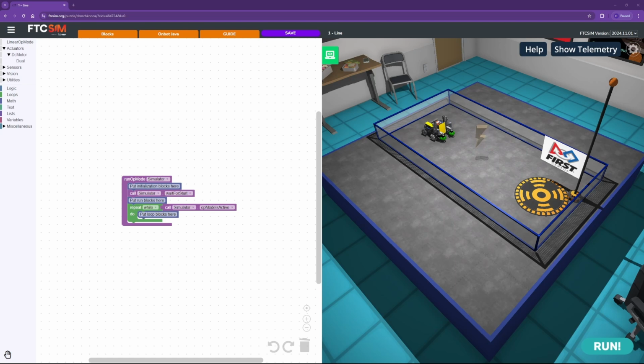This video is more of a how to use encoders in the FTCsim and less of an explanation video on how encoders work. Using encoders is useful so we don't have to use sleeps and motor powers to move our robot. In the FTCsim, moving with sleeps and motor powers is fine, but in the real world, with battery drain, the robot will have less power to drive those motors, making the sleep/power method inconsistent. Using encoders will mean our motors will move the same distance every time.